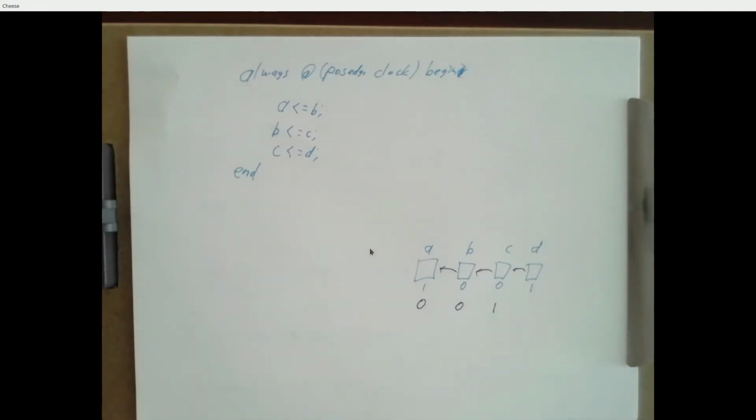This is how you make a digital delay circuit too. If you do music effects and you have a digitized signal, you can take it, turn it into a stream of 1s and 0s, feed it into a shift register, tick it every millisecond. After 1,000 ticks, the thing you put in a second ago comes out the other side. Convert it back into an analog signal and you've got a delayed version. Pipe it back around and feed it in, you've got a reverb unit. So that's how you can do digital reverb and echo.